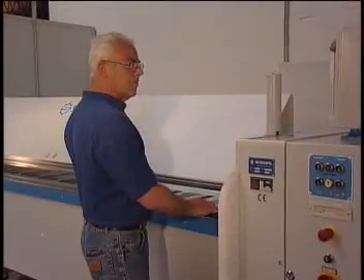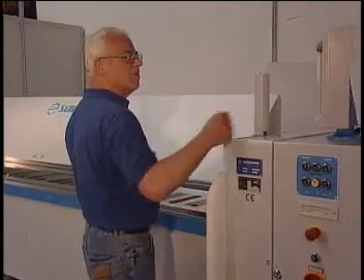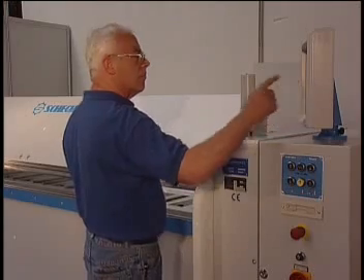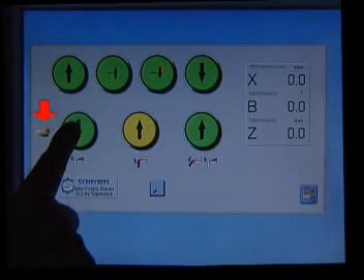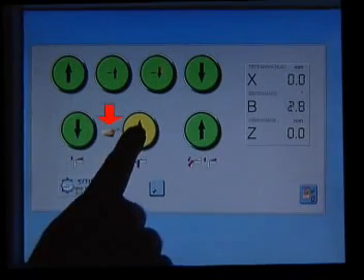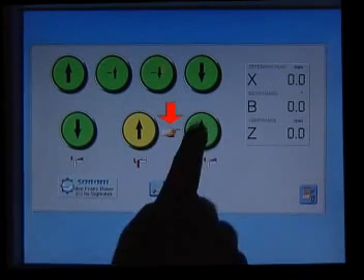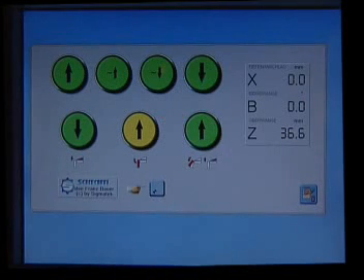After turning on the machine, the startup screen appears. The control has to be calibrated after each startup. Follow the cursor finger and push the upper beam down button, then the bending beam button, and again 2 times upper beam up. Finally, push the back gauge button. Start the actual bending program.